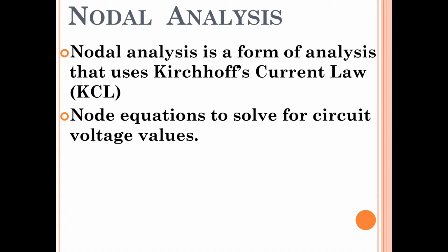Initially we will identify the nodes, how many nodes there are, and count them. Among those nodes, one node we will consider as the reference node, which is also known as the ground node, and the voltage at the ground node will always be assumed to be 0.